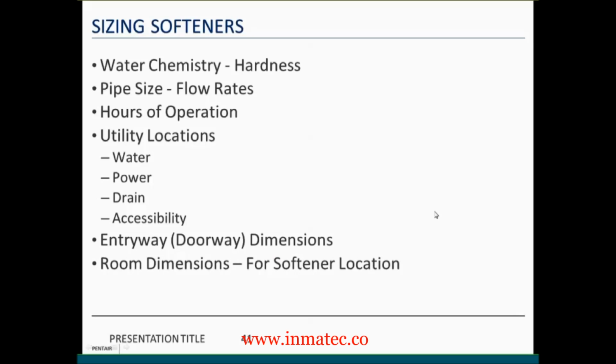Some of these large softeners have massive brine tanks that will not fit through a standard door entry. So you may have to use a man door or a couple different brine tanks in order to match salt use. Dimensions. Will the softener fit in the room? Very important before you sell a water softener. Do you have the space for it?